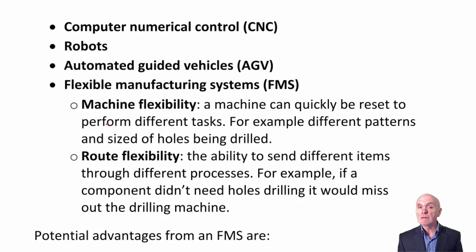So computer numerical control, the easiest example of computer numerical control is a machine which drills holes. You can put the product on the machine, and on numerical control, the drill comes in and drills holes at precise locations. Another example is maybe cutting metalwork. You've got your bit of metal there, and under computerized numerical control, in it will come and cut out holes and gaps and so on, completely automatically.